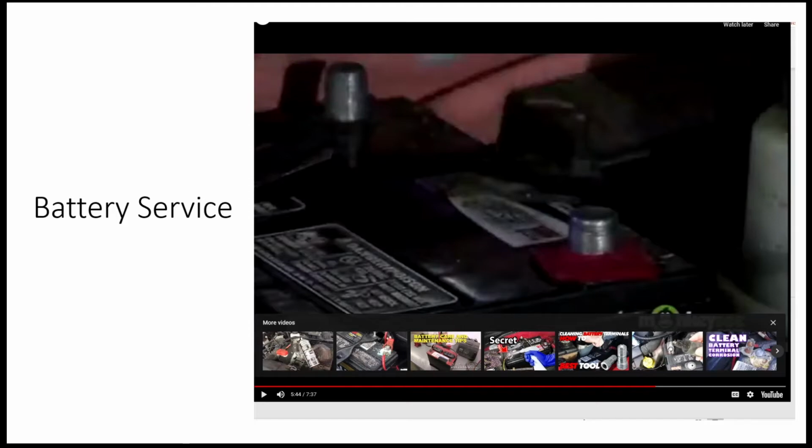My suggestion would be, and this is my official suggestion, to put a drain pan underneath the car, underneath the battery area, and wash the battery off and let it go into the drain pan and capture that water and dispose of it properly in accordance with the regulations of your shop and the state and environmental concerns. So get rid of it properly and clean the battery properly so that it's maintained properly.